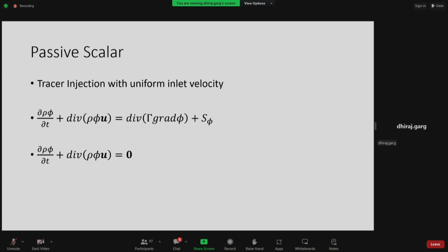Another thing I would say, as we have seen in previous equations: unless density and viscosity are changing, the systems are considered decoupled. Decoupled means they can be solved individually, so they need not be solved simultaneously. But if the density and the viscosity are changing, that means they are a coupled system. That means you have to solve them simultaneously. You cannot evaluate them independently.